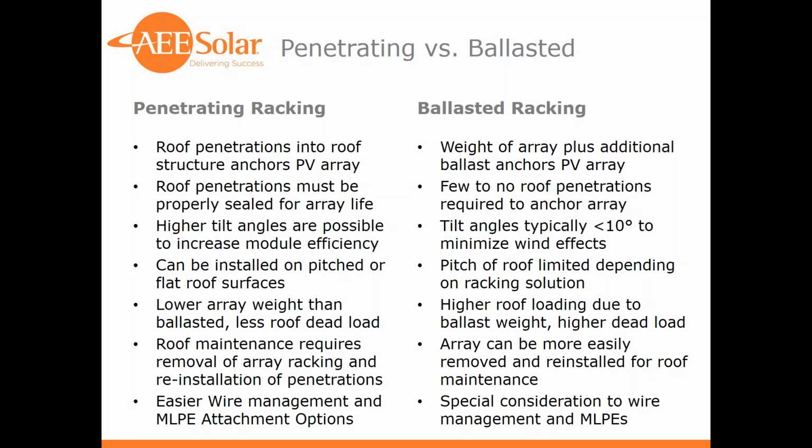Roof maintenance for penetrating racking often requires the entire racking and the array to be removed prior to servicing the roof. With ballasted racking, we can just remove a small portion of the array and service the roof right at the point where it needs to be serviced.